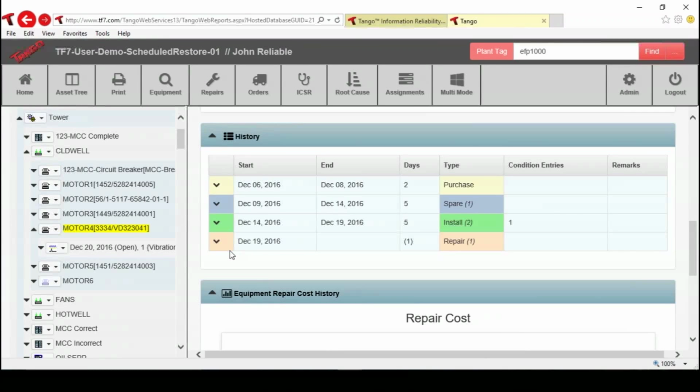So that's essentially the mechanism of tracking. You've got a piece of equipment, you've got an inventory of equipment, you decide what's going to go back into that location when you remove something, so you see that it's not trivial. It's not a trivial set of work. And so you don't want to do this for every piece of equipment in the plant. But there are good reasons to do it for large, critical, warranted, repairable equipment.